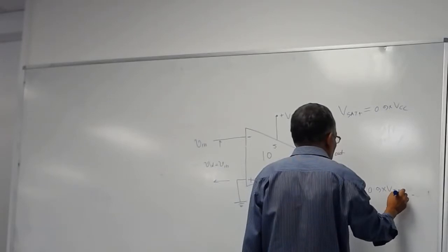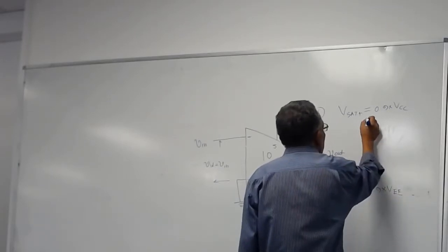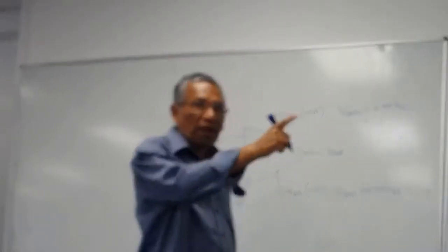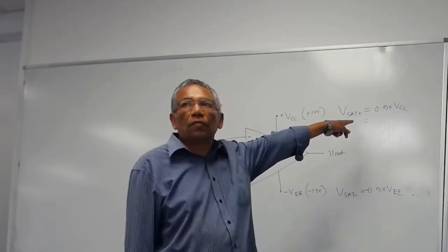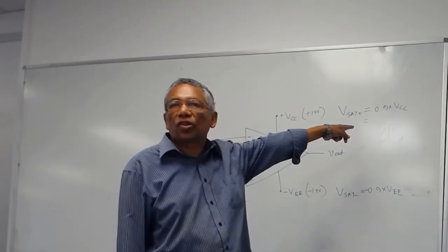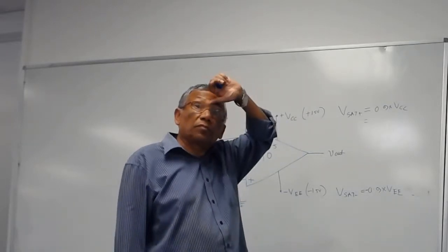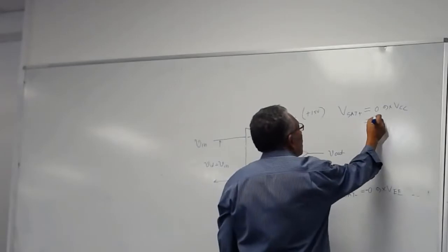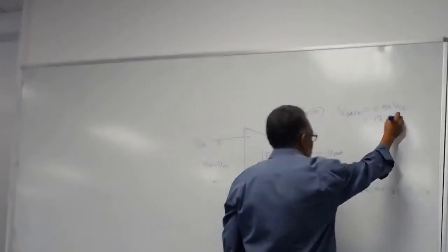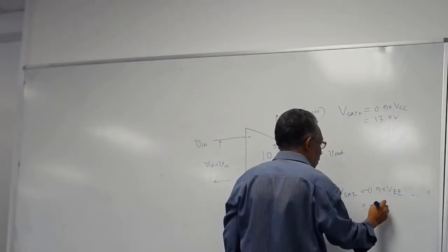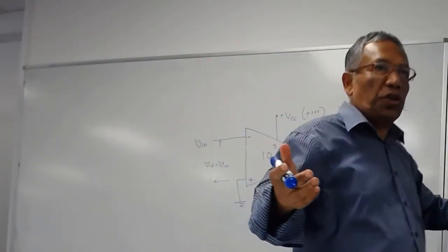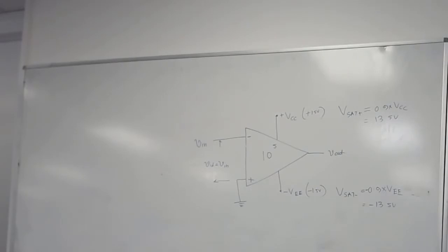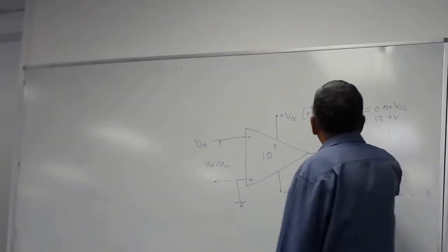So how much is this? 13.5 volts, and this is equal to minus 13.5 volts. So it will saturate to that voltage. It won't go up to the full 15 volts plus or the full 15 volts minus.